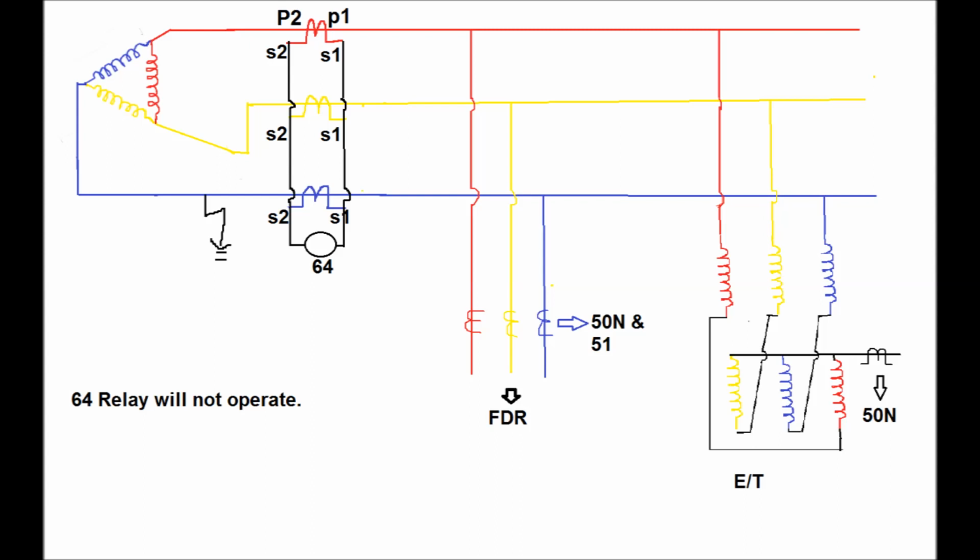Otherwise the earth fault remains in a hanging condition and there will be voltage stress or voltage overshoot in the healthy phases until and unless the earth fault is removed.